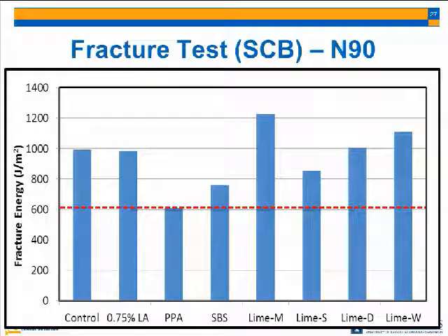When you heat the aggregate, we say 300 degrees, but actually in the plant itself you have a shock of high temperature of 600 degrees Fahrenheit. You have this big wave at 600 degrees that is just for a few seconds, and then it's cooled down. So the temperature is like half of this in the mixing barrel. It will be at that time around 300 or 310, whatever.